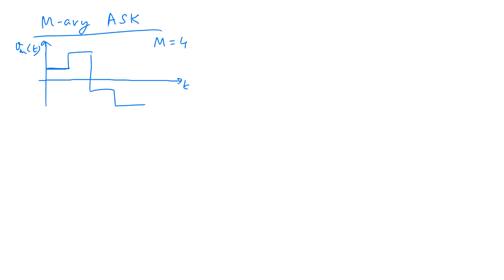So we have 4 voltage levels, and if we call those voltage levels simply as, say, V1, V2, V3, and this is V4, right? So there are 4 voltage levels to represent the 4 symbols that we are going to transmit. And if we had such a signal modulating the carrier, that means the carrier signal, depending on which symbol is being transmitted, it will have 4 different amplitude levels. So after the carrier gets modulated, I'm just going to draw it in sequence. Don't compare this with the message signal as it is.